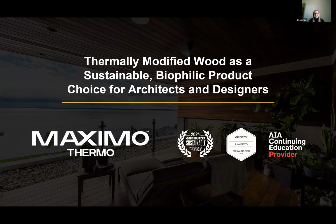Okay. All right. Is there any difference from a workability standpoint of working with thermally treated wood? No, I think it glues very nice. Your typical polyurethane type glues work really well with it. Some, like a Type Bond 3, work better than a Type Bond 2. So Type Bond 3 is more water resistant, whereas Type Bond 2 is waterproof. So I would look at that.